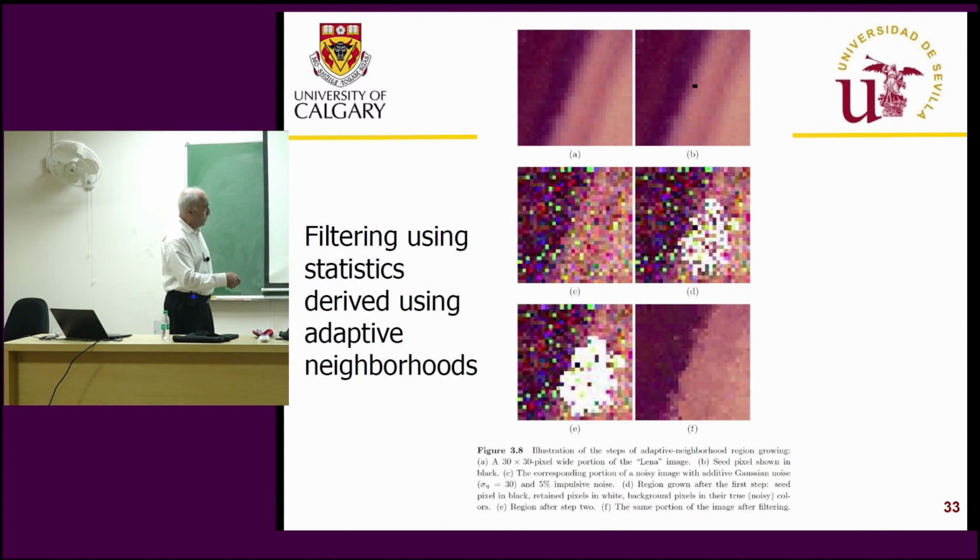There are still a few pixels that are not included because they differ by substantial amounts compared to the seed. So that is the region. And when you average this, you get a clean pixel value. And when you do that for this image, that is the output. So the effect of noise, you see all these other colors, has been suppressed. The edge has not been blurred substantially.